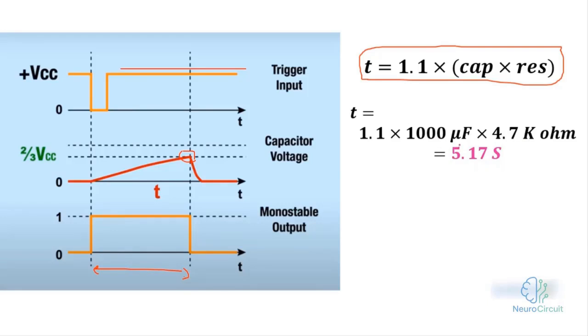Regarding unit conversion, let me say that here we have a capacitor and here we have a resistor. Obviously, their units are not the same, and there's really nothing that requires us to convert farads to ohms. But the point is, we have microfarads and kiloohms. We know that micro means 10 to the power of -6, and what about kilo? Kilo is 10 to the power of 3, so we can apply these coefficients so that the units are in farads and ohms, which will give us the output in seconds. And when we multiply by 1 and 1, we get this value now.